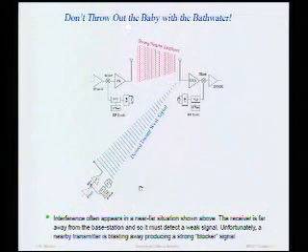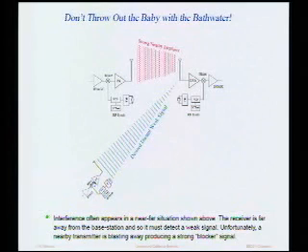So this is called a near-far situation. You're near an interferer and you're far away from the desired signal. And so this means that your receiver has to be able to deal equally well with small signals, which are very close to the noise, and large signals, which in fact excite nonlinearities in your receiver. So that's the key word, nonlinearities in your receiver. And this is something that we'll talk quite a bit about in this course.